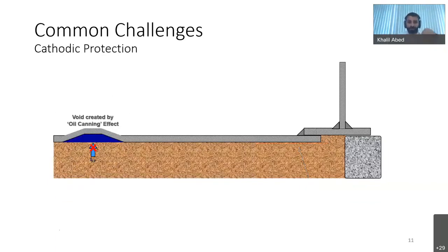This is in case tank owners utilize cathodic protection for protecting the tank bottom plates against soil side corrosion. The presence of shielding material, or even the inevitable air gaps caused by the canning effect, filling and refilling cycles, or settlement in the tank pad, doesn't allow the CP current to reach the underside of the tank floor and polarize the structure to the protective potential.